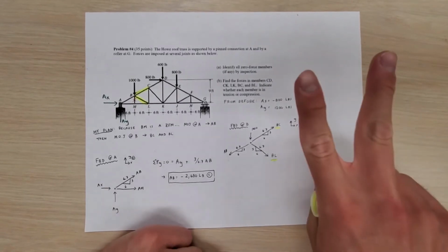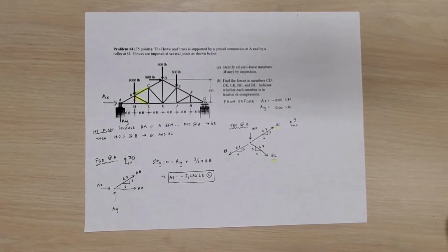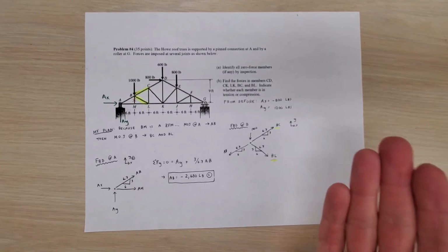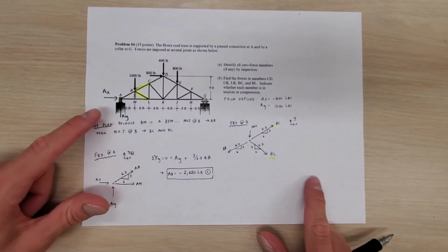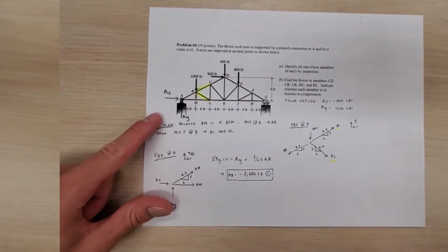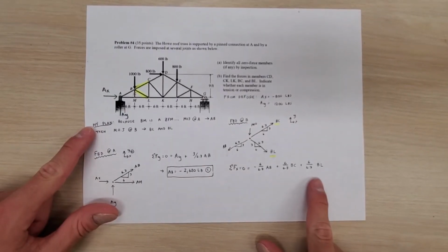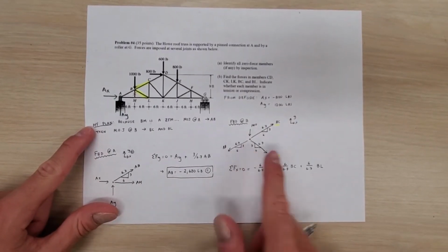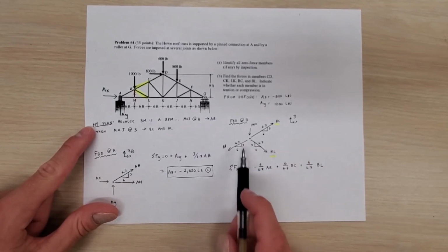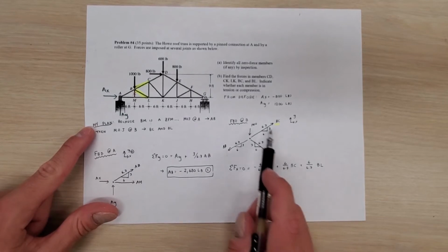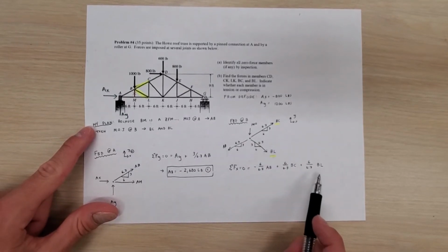So I need to write two equations to solve for those two unknowns, and those two equations are going to be the sum of the forces in the x and the sum of the forces in the y. So let me set up the sum of the forces in the x equation and show you what you would do after you did that. So I've got my sum of the forces in the x, which is 6 over 6.7 of AB, BC, and BL. AB is negative because it goes to the left, I've said, and BC and BL, I'm assuming, are going to the right, so I've got those as positive.